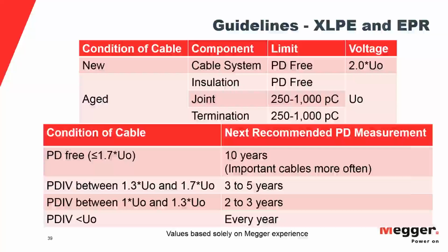Just a little comment to that. Square wave, just to make this clear one more time, is not the same as cosine rectangular, and a triangular wave, for instance, is not recognized by any test standard as well. There were some experiments with this, but it never got anywhere. So a triangular wave VLF is not supported by any standard anyhow.